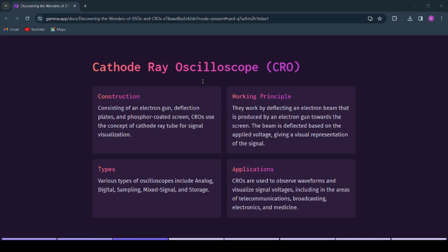After the emission of an electron from the cathode, it passes through the control grid. The control grid is usually a nickel cylinder, centrally located and coaxial with the CRT axis. It controls the intensity of the electron beam emitted from the cathode. The electron, while passing through the control grid, is accelerated by a high positive potential which is applied to the